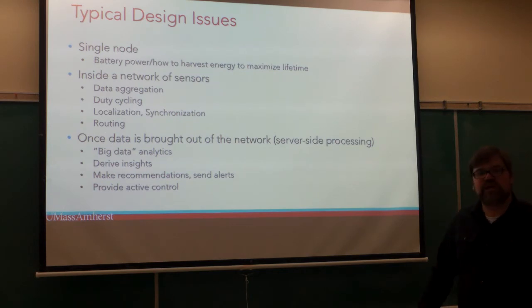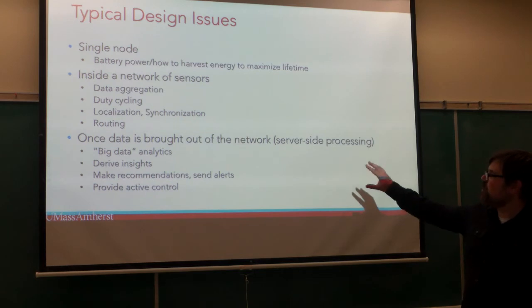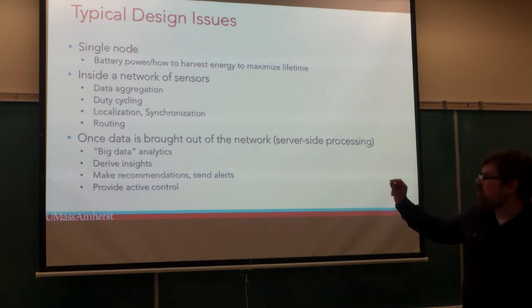Or maybe you bring into it something about the remaining battery life on a node, right? So maybe I don't want to transmit data to a sensor that has a battery that's more depleted than the others. Maybe even though another sensor has a higher packet loss rate, it has a lot more battery power, so I decide to route to that node instead. So there can be a lot of different ways that you might want to optimize routing in a sensor